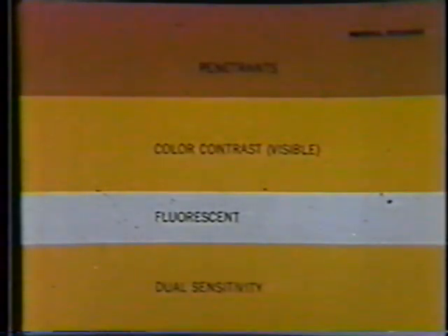For greatest sensitivity or seeability, fluorescent penetrants are used. They contain dyes that fluoresce when exposed to black light. The penetrant color is usually green. The fluorescence, a bright yellowish green. For special applications, there are fluorescent penetrants that glow red or blue.